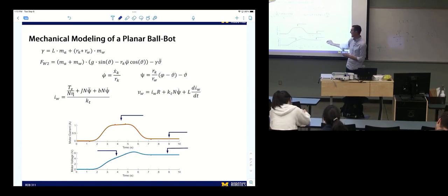And so what would this entirely be, or almost entirely be? What term in the motor's voltage equation? Back EMF. So at this point it's spinning fast. It's ramped up to a constant velocity. At this point, I should have put the ramp function, but it's just spinning really fast under no acceleration. It's reached the plateau of the ramp.